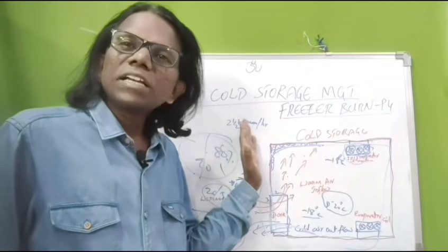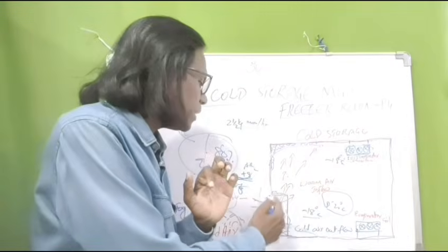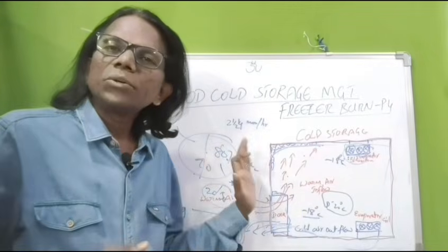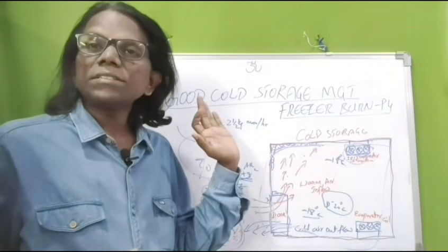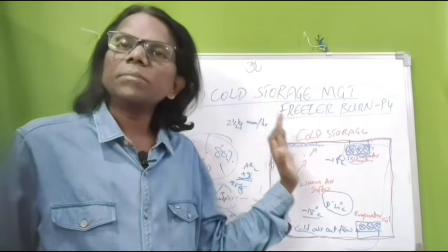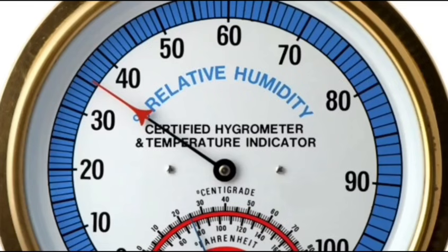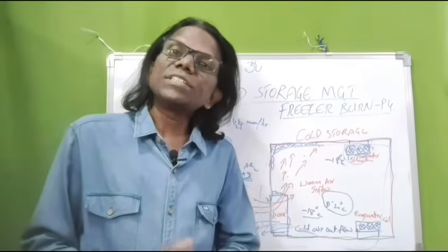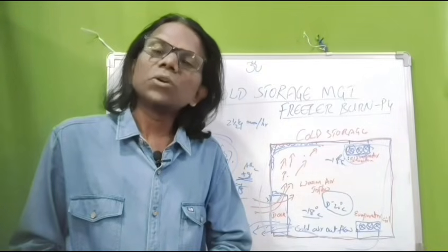And controlling the relative humidity means if we can reduce door opening times, arrest door gaps, and minimize the number of door openings and the warm air entry, then we can extend the product shelf life, and reducing the running hours of refrigeration units will give us good results.